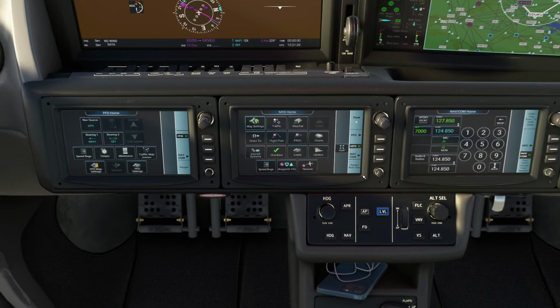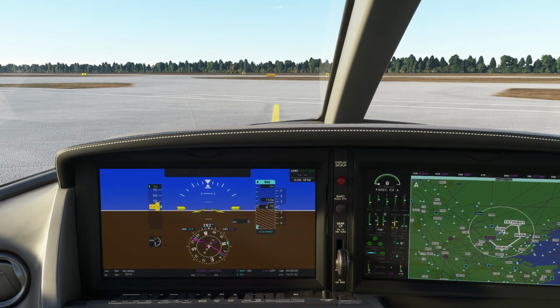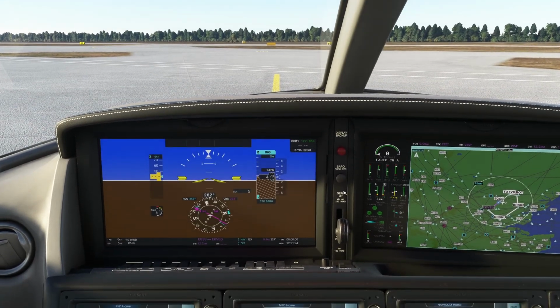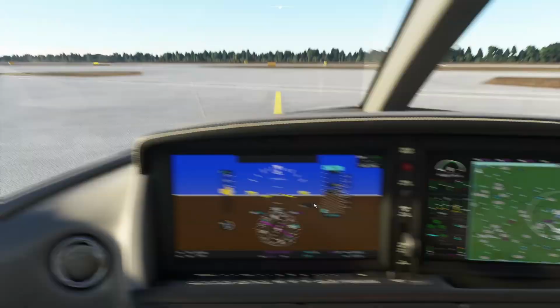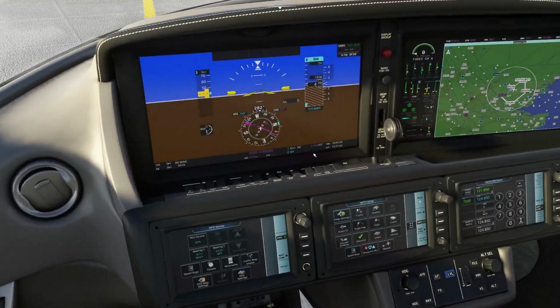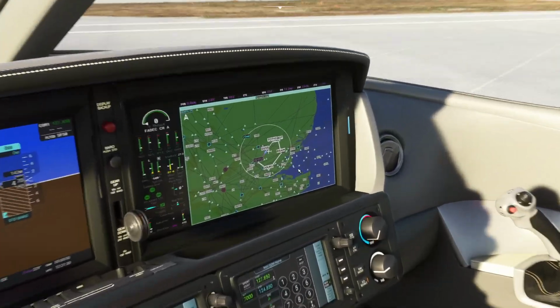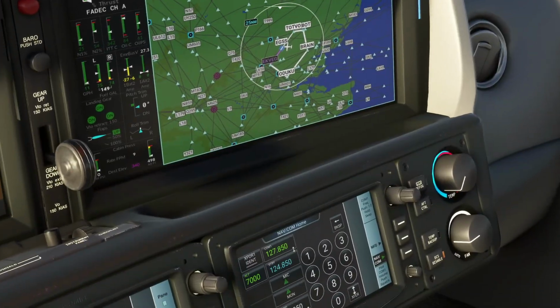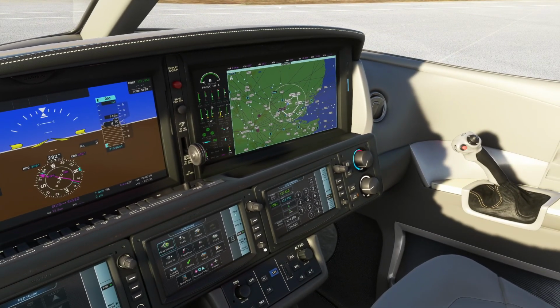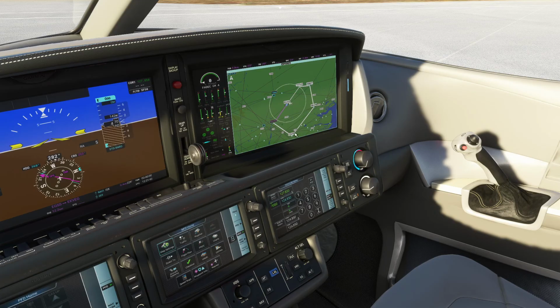Anyway, let's come back out. So runway 22 is 222 degrees on the compass, but we've got a flight plan which you can now see, by the way. And if we use the knob at the bottom right of the MFD, the multifunction display, we can zoom in. You will notice the next leg is in magenta, so that will update as we fly around the flight plan, showing what the next leg is all the way.